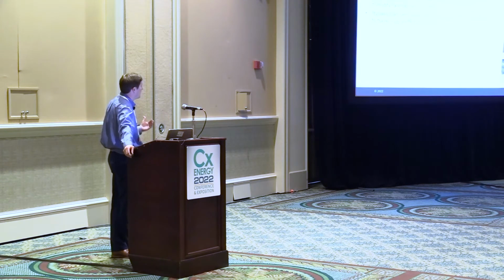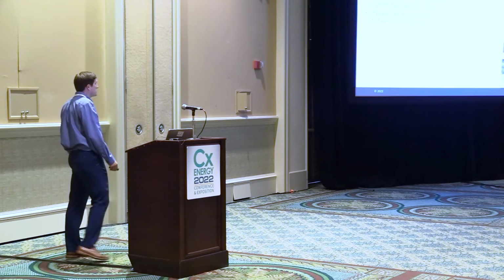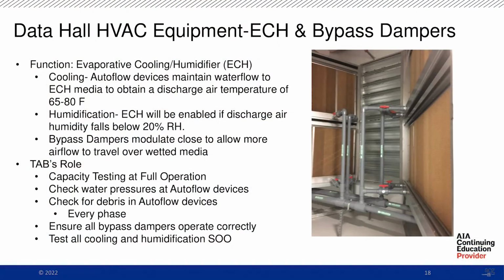because right after this is going to be our fan array. So as we look at our fan array airflow measuring, it's going to be very important for us when we're doing our testing that these dampers are actually closed.